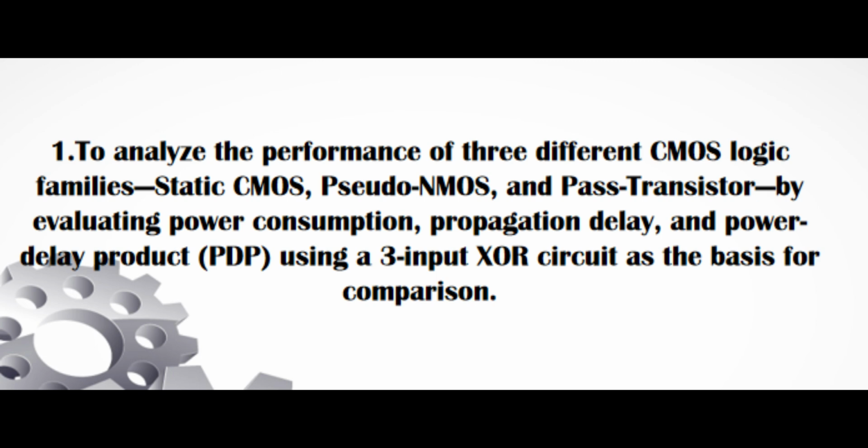First is to analyze the performance of 3 different CMOS logic families, static CMOS, pseudo-NMOS, and pass transistor, by evaluating power consumption, propagation delay, and power delay product using 3-input source circuit as the basis for comparison.